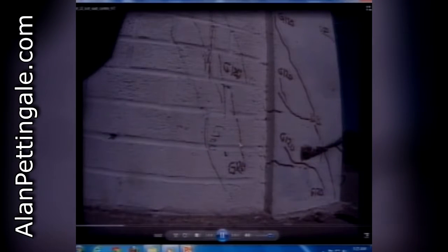And that's my last video. That's a close-up of that column. So this is the wall that you saw falling apart, and this is a concrete column next to it. And this is not to tell you that an earthquake is to occur here in Brownsville, but I really want to point out how in a building things work together. So it's not that we can just ignore masonry or parts of the building, saying that that's not going to take any load. We really have to consider the behavior as a whole, no matter what the load is. And here you'll see why.